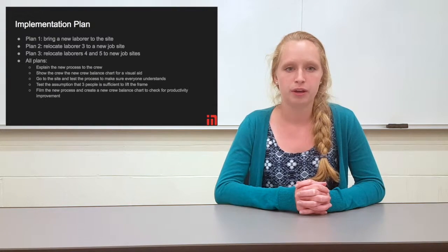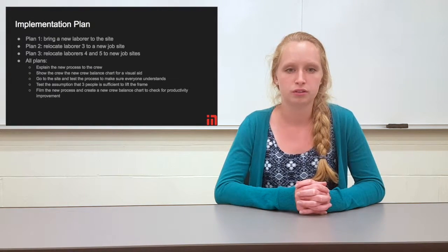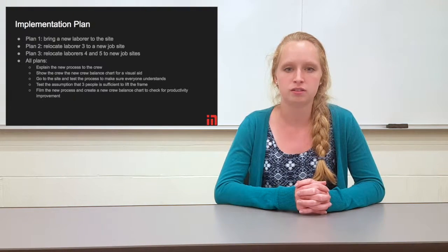For each new site, we would have to explain the process to the crew, show the crew the new balance chart, go to the site with the crew and test the new process to make sure everyone understands, test the assumption that 3 people is sufficient to lift the frame, and film the new process to create a crew balance chart to see if there's a productivity improvement.